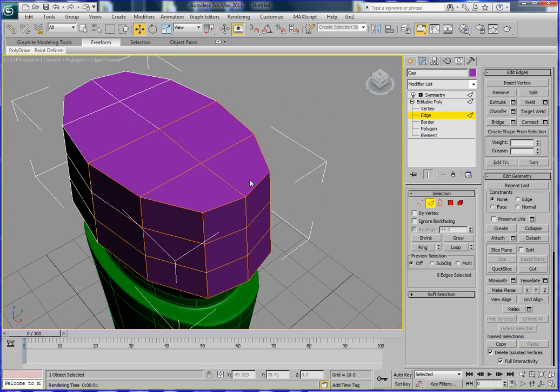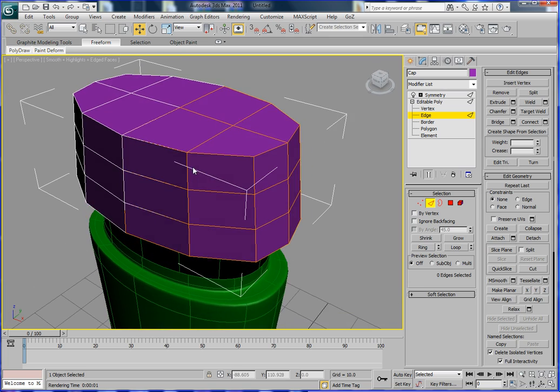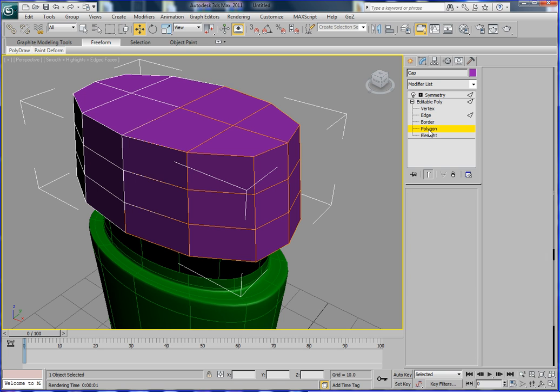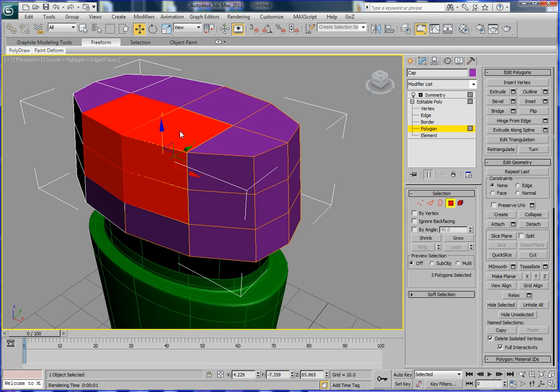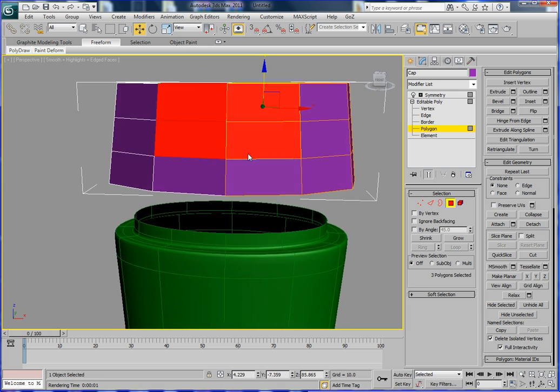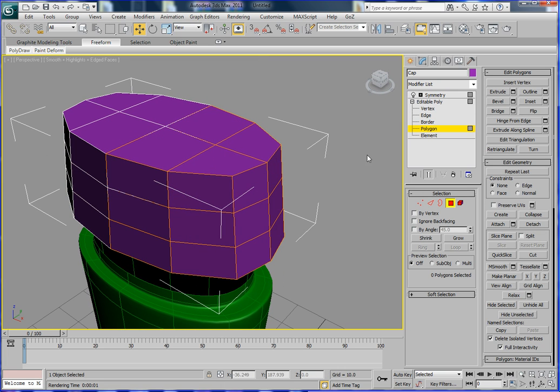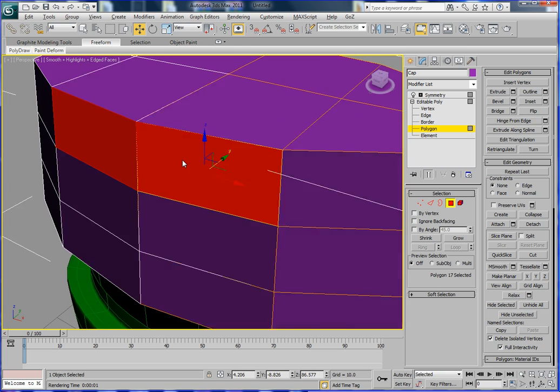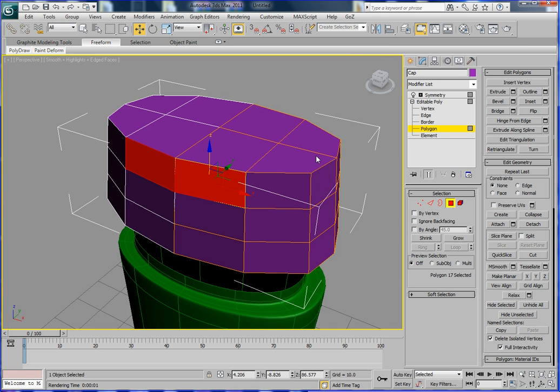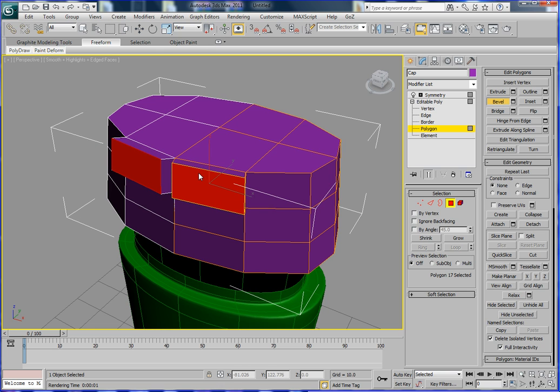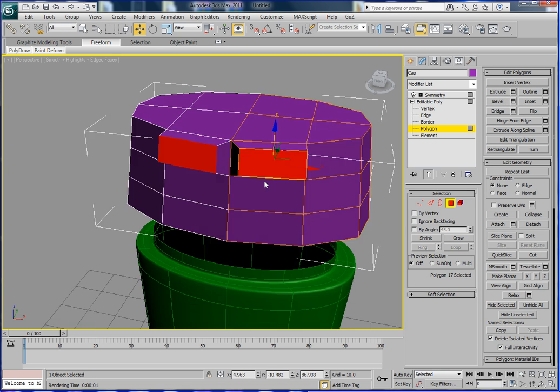So now when I think about it, I plan to basically do like this. This polygon will be the cap, alright, but I want to add some fancy shape a bit by extruding this polygon so that there will be a grip for our finger to actually pop it open. So I'm going to use the bevel. Just gonna bevel this. Okay, don't worry about the shape, it's not correct yet.